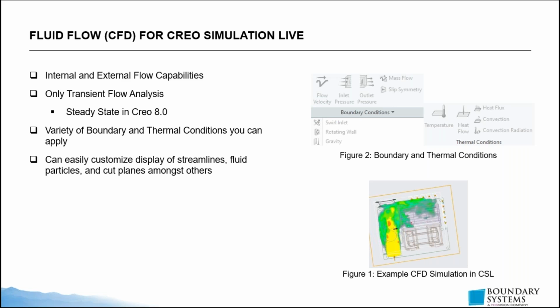And so you can display streamlines, you can put fluid particles in, you can have cut planes, but in this case, instead of applying a force and looking for stress, you're saying, hey, I have air flowing or water flowing at a certain flow rate over a certain geometry, let me know what my pressure drop is or things like that. And again, this does not replace the full-fledged Creo Flow Analysis extension, which is its own analyst-level CFD tool that can handle much bigger, much better physics.